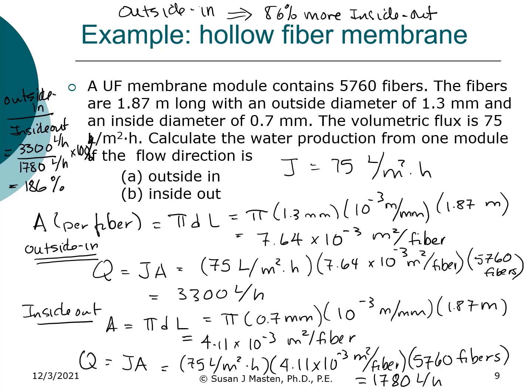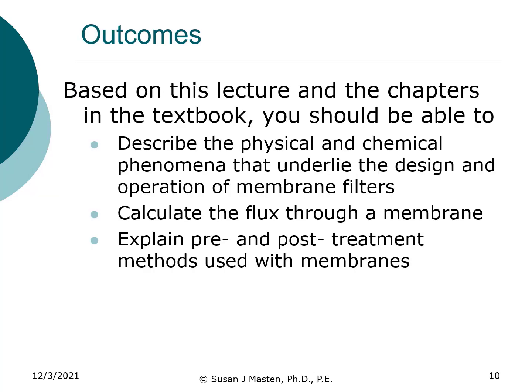And as I've showed previously, with the membrane bioreactor, you can see those operate as an outside-in. Most of the work that I've done with ceramic membranes actually operates in an inside-out configuration. So the flow is into the tubulars of the membrane, and then out through the outer walls. So hopefully this helps you have some better sense of how we design and operate membranes, and will also help with the homework.